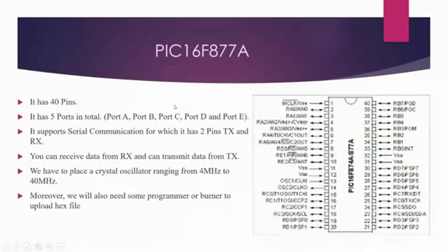The PIC16F877A microcontroller has 40 pins and 5 ports in total. It supports serial communication, for which it has 2 pins, transmitter and receiver. You can receive data from the receiver and transmit data from the transmitter. We have to place a crystal oscillator ranging from 4 MHz to 40 MHz.